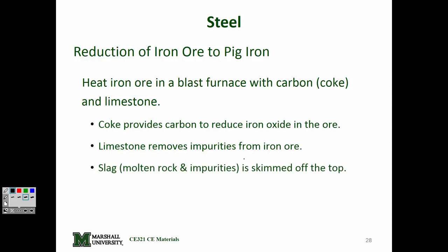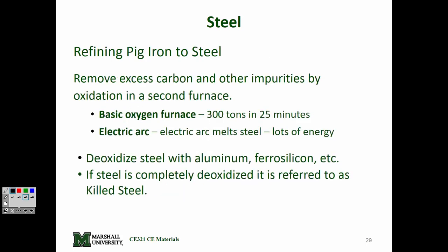We're going to pull those off in the form of slag and technically throw it away from a steel making standpoint. We can use that in other applications. Put it in concrete, put it in fills and things of that nature if it's controlled correctly. And we take the molten iron, and typically it's decanted off the bottom of the pot so they don't contaminate it with any of this slag we have on top. And they'll sacrifice a little bit of steel in the pot just not to contaminate what they move on to the next level. So they'll decant it off the bottom and move on to the next process.